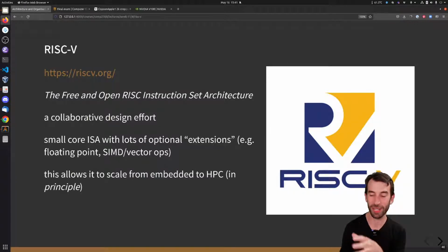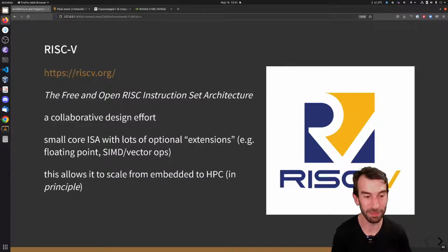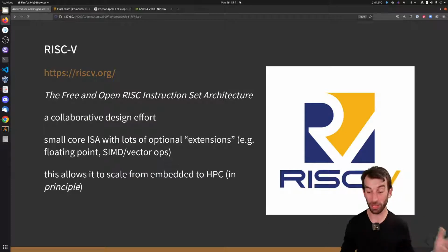This is sort of in contrast to the x86 Intel architecture, which is really complicated. It's often called CISC, complex instruction set computing, which has a lot of instructions, but even compared to x86, even with all the instructions that your Cortex-M4 has, it's still considered to be a fairly tight ISA.